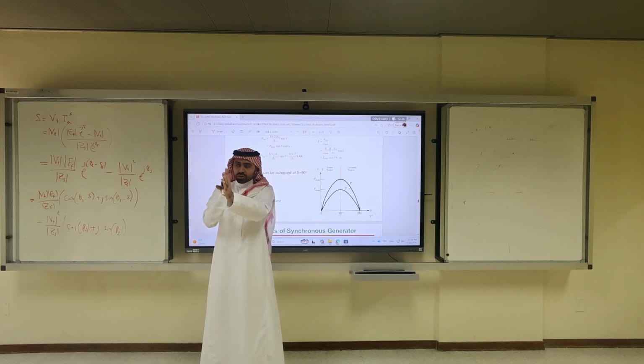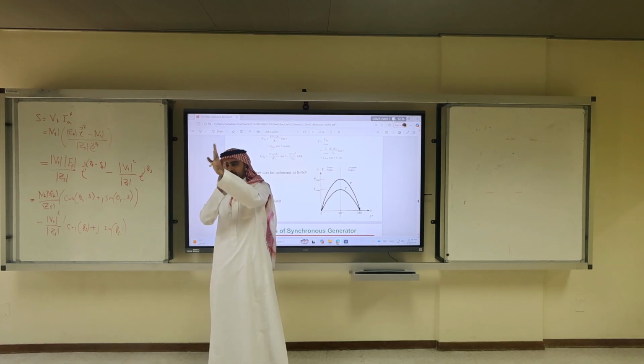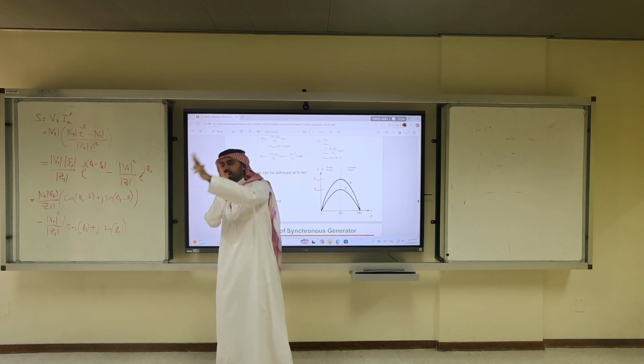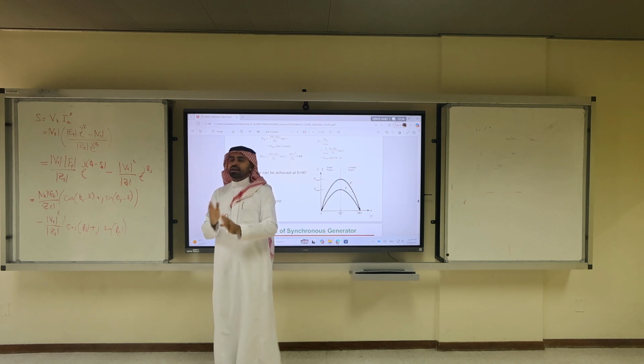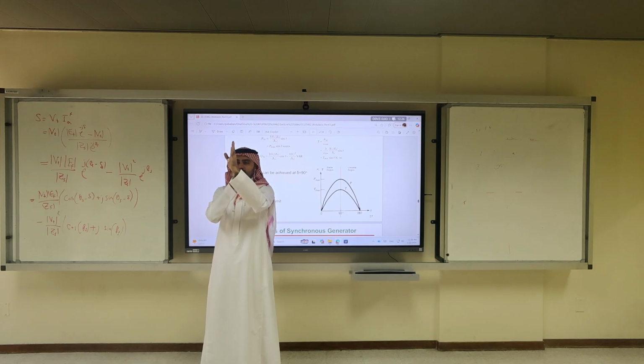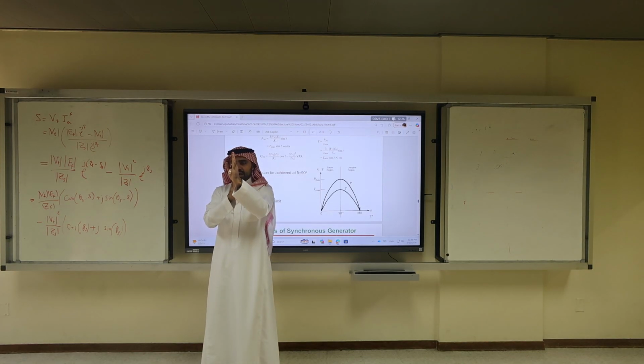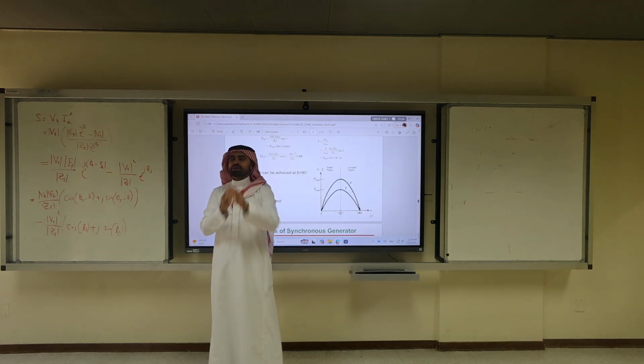Where you synchronize your magnetic flux, the moment you decide you're spinning your rotor, the moment you release it, you have to make sure it is aligned. The magnetic flux are aligned to get the maximum power. If the magnetic flux lines are not aligned, they were rotating, but they will be dragging each other. Your goal is to make north with south aligned to each other. But for some reason, if you make it aligned to each other, this is difficult to synchronize. They would drift away if you change the load, etc.